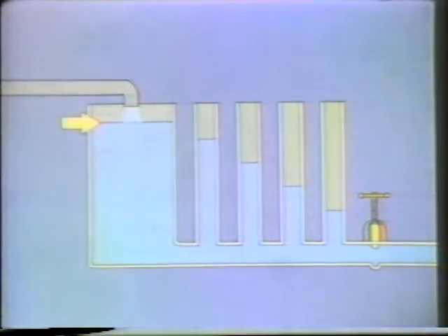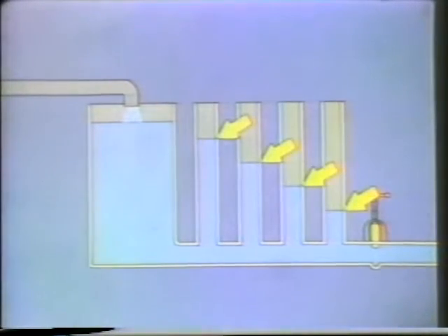We'll open the valve and at the same time start a flow of fluid into the tank to keep the tank level constant. As we do this, notice that while the level in the tank remains constant, the level of fluid in each standpipe decreases. The decrease in level means that the further the fluid must flow in the discharge pipe, the greater the friction head. Friction head, velocity head, and static head determine total head on a system. Total head is defined as static head plus velocity head minus friction head.